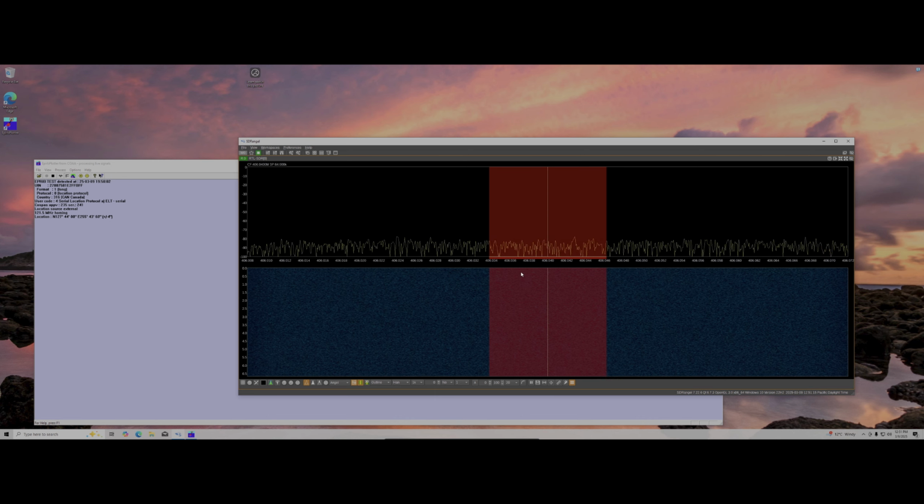The only caveat is sometimes, depending on the ELT manufacturer, there's going to be a different range that it outputs on. So you'll be able to see that in your waterfall, but because this is our narrow FM, this is what we're specifically listening to with the RTL-SDR, it might not pick it up as well. Some ELTs transmit over here kind of between like 406.025 and 028, so kind of in this range.